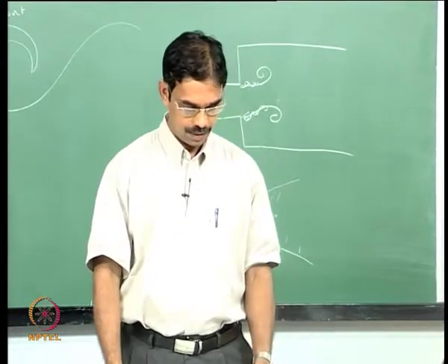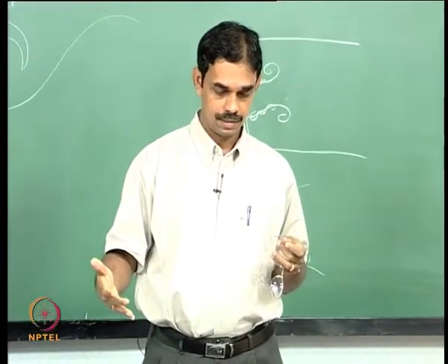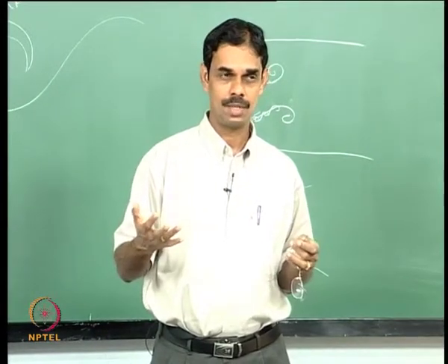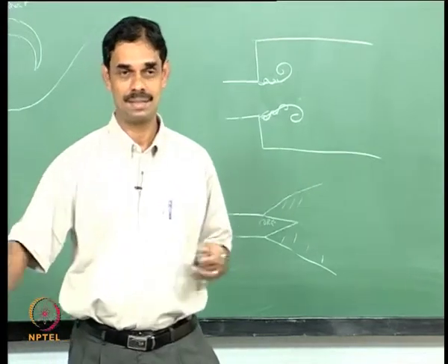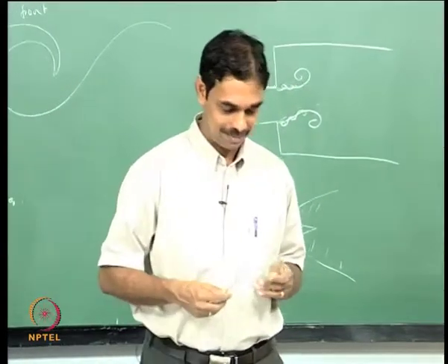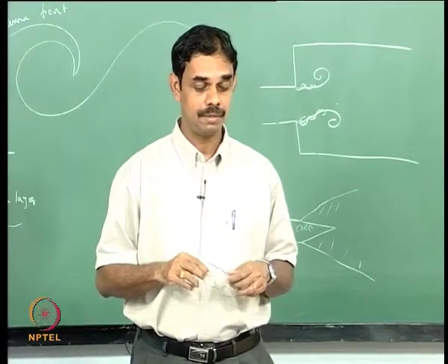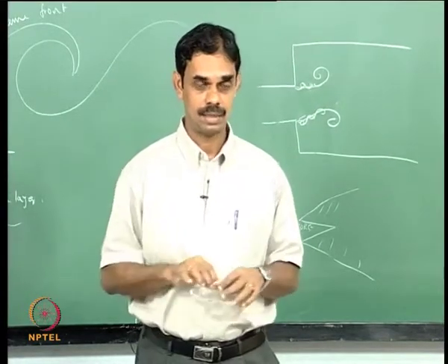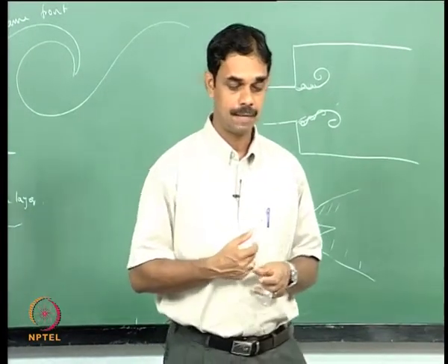So you have the developing vortex go downstream of the dump and impinge against the wall, and again impinge is a very crude term. It is like one shear layer interacting with the boundary layer when it comes close to the wall, so it does not mean it just goes and bang hits. Since the downward velocity of the vortex is large, a vigorous mixing occurs between the remaining unburnt reactants and the combustion products, again leading to a sudden heat release as this mixture approaches the wall, and the energy is supplied to the acoustic field if the heat release oscillations are in phase with pressure oscillations.